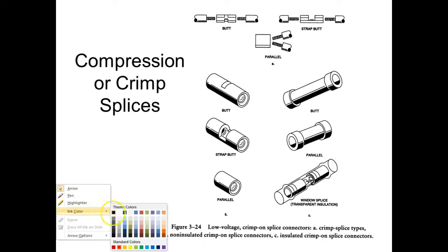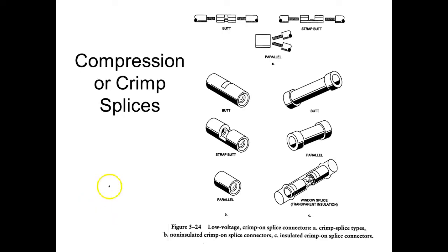The one that punches through, you want it away from the seam. So you've got a seam right here, and you want the round side on this side. Because if you crimp into that seam, it's going to separate. You want to push that barrel down into this side, which actually forces the seam together and doesn't let it split apart. If you flip that around and crimp on the seam side, it's going to spread the seam apart. Guaranteed.